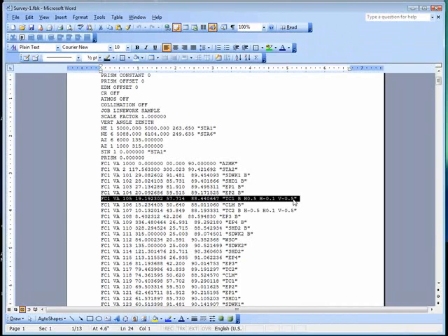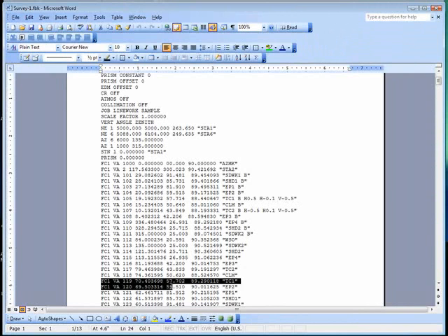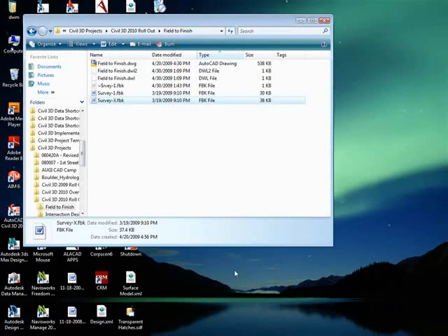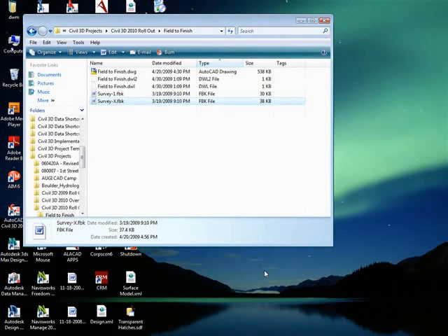With our new technology that we have inside of Civil 3D, we can actually create line codes, and in those line codes, this information, the H's and the V's and the B's, actually stand for a command inside the survey language. So here we're telling it we're beginning a top of curve, but we're also offsetting that line, this amount, horizontally and vertically. And until we end that command, every time we have a TC1 point in our drawing, we're going to get that same offset applied to it. So let's close that out, and let me get back to Civil 3D.